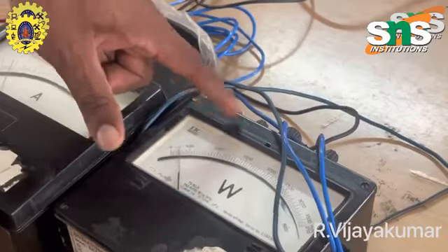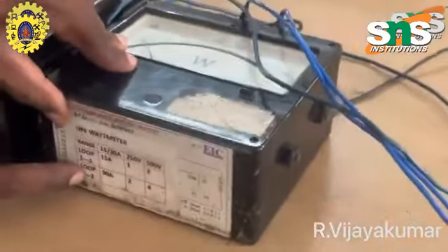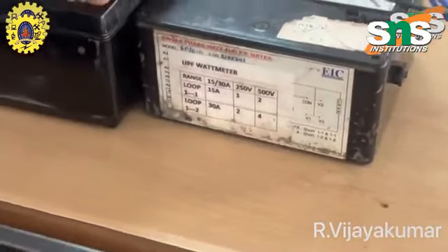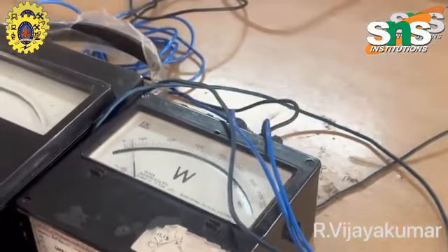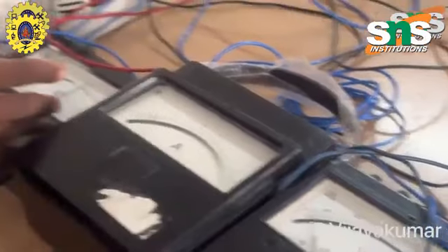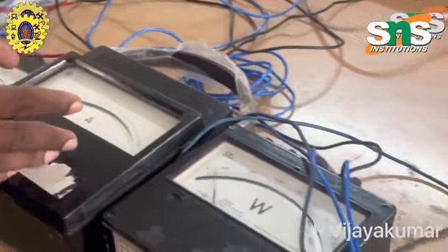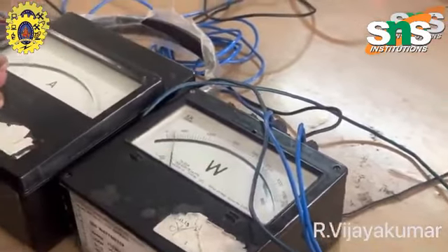Now terminals 1 and 2 are connected. From the wattmeter table, for terminals 1 and 2 connected at 250 volt, the multiplication factor is 2. So I calculate 300 into 2, which is 600 watts. That means my load is consuming 3 amps of current supplied by 200 volt, and finally it gives 600 watts. That 600 watts is exactly what the unity power factor wattmeter shows.